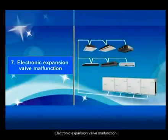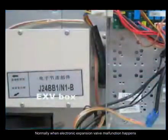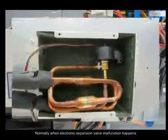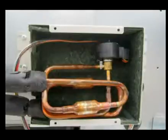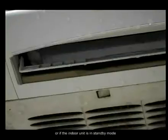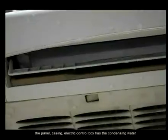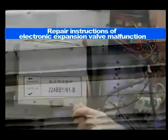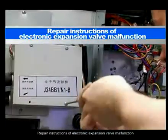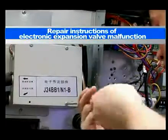Electronic expansion valve malfunction. Normally, when an electronic expansion valve malfunction happens, the cooling or heating performance will be bad, or if the indoor unit is in standby mode, the panel, casing and electronic control box have condensing water. Repair instructions for electronic expansion valve malfunction.